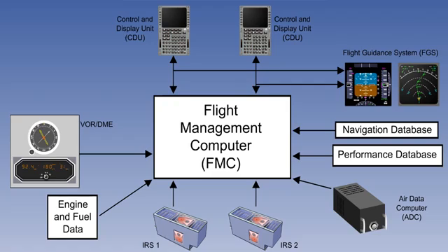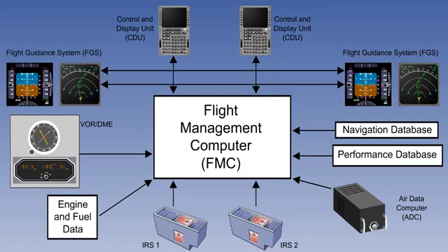This is a generic term which can either mean the flight director display on the electronic flight instrument system, or can mean the autopilot. This is the layout of an early model of the FMS fitted to the Boeing 737-400, and although it did not have GPS, it was very similar to our basic model. You can see that there is one flight management computer serving both pilots and 2 inertial reference systems.